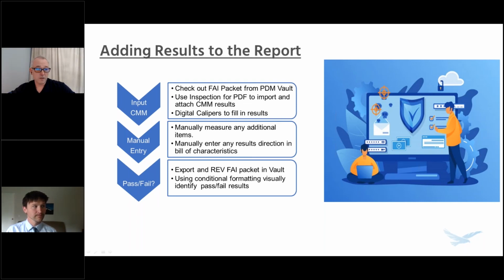So that's all stored in the vault. Not only is the drawing and the inspection project, but also that PDF, that Excel file, and data. PDM is going to manage all that data, one source of information, and then from there we can use a CMM to measure those parts that are going through the process of trying to approve these for manufacturing, and then we can read that back into inspection and see if it passes or fails, and then store all that information in the vault and keep it revised.